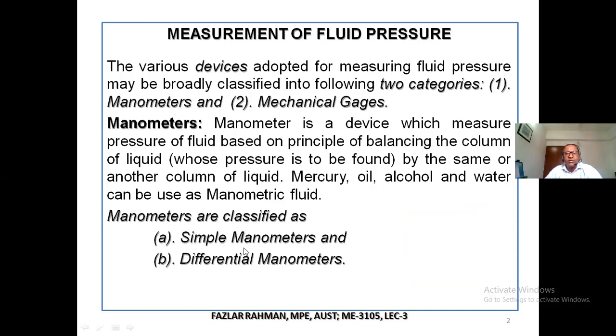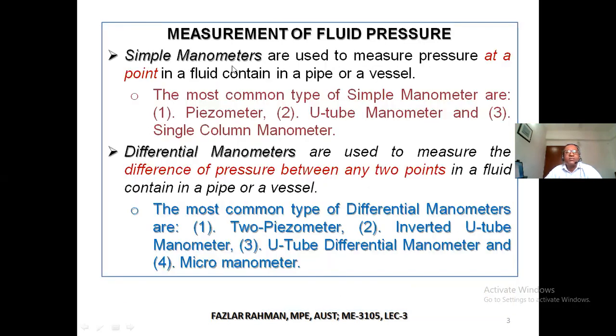Now we need to check what is a simple manometer and what is a differential manometer. Simple manometers are used to measure pressure at a single point, in a single pipeline or a pressure vessel. That is called a simple manometer. Most commonly used are the piezometer, U-tube manometer, and single column manometer. We'll show you how the simple manometer and differential manometer look.